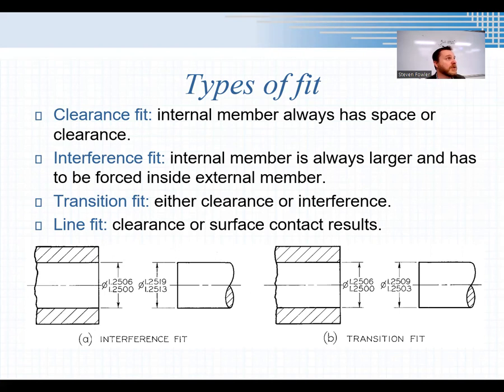If we send them to the printer as an interference fit, sometimes we have to sand a lot of material off to get them to fit the way you want them to. So a lot of times what we'll do is cut just the pieces that are going to fit together out of your entire design, not print the entire design, just print the parts that are going to fit together, and make sure that you get the fit that you want. Then we can mess with the tolerances there and go from there.